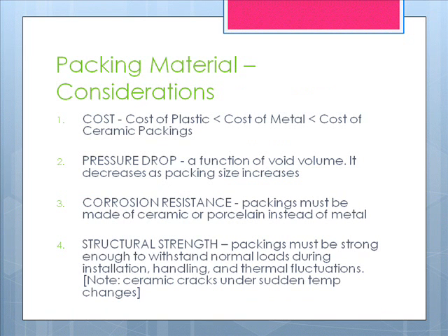It is also important to consider the type of packing material that will be chosen for a specific process. Some considerations follow. Number 1, cost. Plastic packings are generally cheaper than metal, and metal packings are cheaper than ceramic.